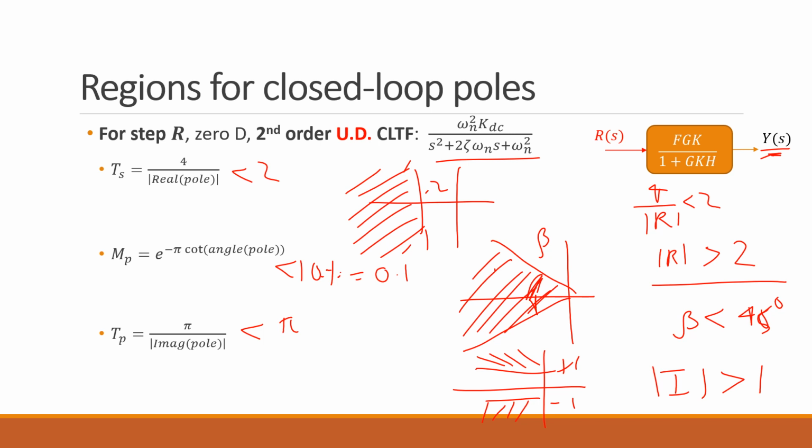Now, all these formulae are only for second order systems. If you have a higher order system, then we're going to shamelessly use the second order formulae as guidelines, but we must still remember that whatever these second order formulae predict as the regions for the poles to be, we have to take that with a grain of salt and consider the effect of extra zeros and poles.